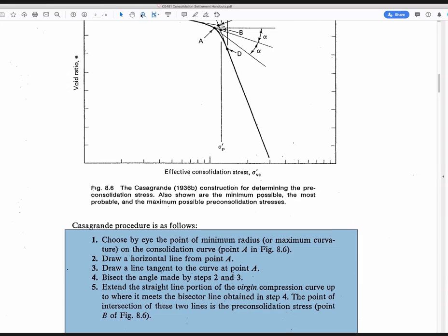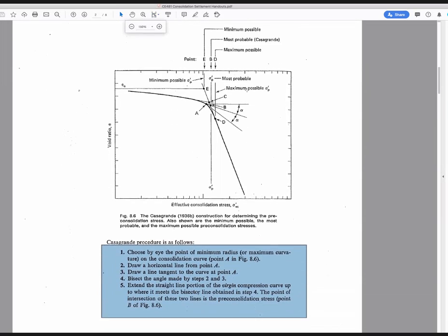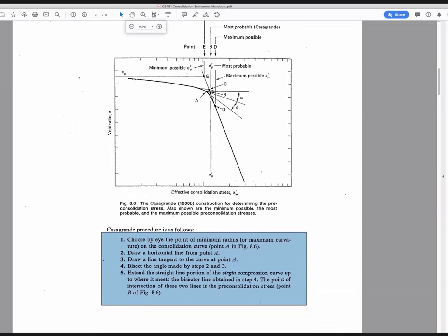And let me get this down in size a bit so we get it all on the same page here. And this is your consolidation curve. Okay, so up until now, we've just been calling it a knee of the curve and saying, hey, it's right there at the obvious knee, but there's some refinement to how you can get to an actual value for that when you're dealing with real data and you have some curvilinearity to this shape.